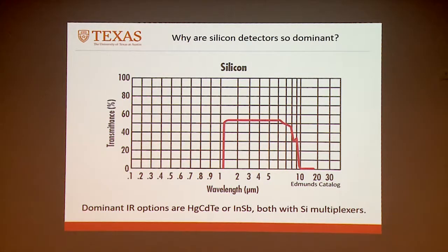And silicon has this interesting property, which is right at about 1 micron, it becomes transparent. The reason I'm mentioning this is it'll become very important later when we talk about the immersion gratings. But because it becomes transparent, it doesn't absorb light, and therefore silicon detectors stop working. And so you'll often find a technology boundary right at a micron. So the optical will go right to just past a micron, and the infrared will start there simply because that's where you can't use silicon detectors anymore.